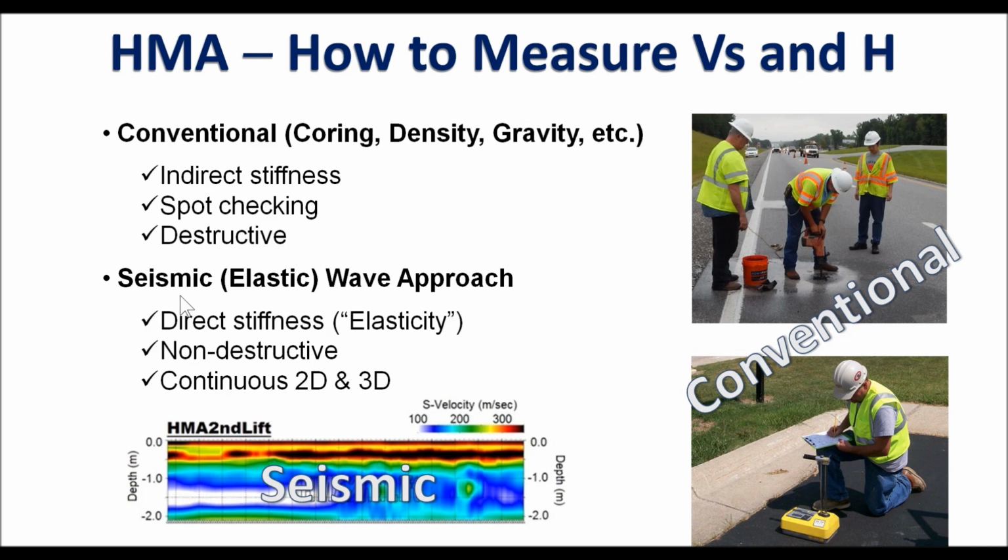Whereas this seismic approach will be dealing with the seismic waves, also known as elastic waves, which are responding to elastic properties of materials. So this elasticity is a lot closer property to stiffness property. And it is a wave approach, which means it can scan on the surface, which becomes a completely non-destructive method, and the measurements can become continuous so that we can generate 2D cross-sections or 3D scanning maps.